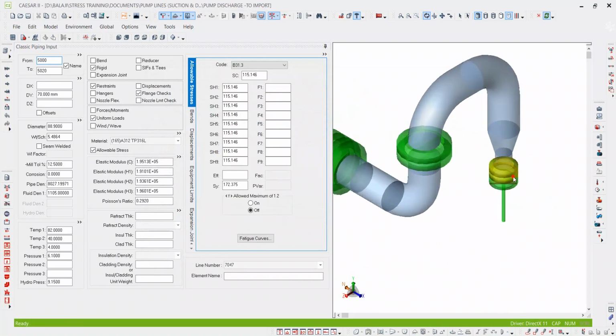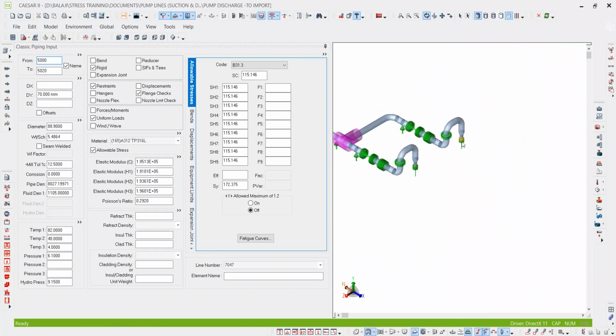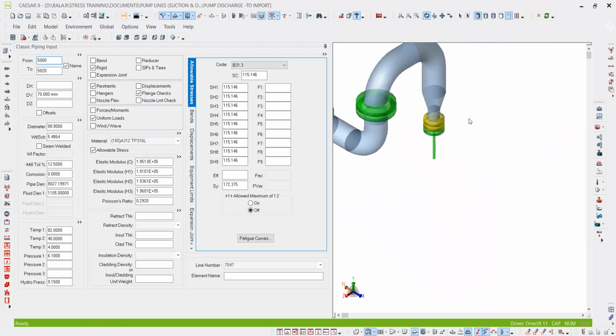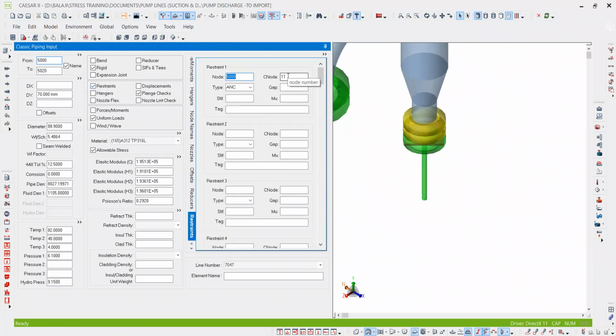So here, what we need to do, that's what I told you clearly. The node number, whatever you use for the other file, should not get repeated. If even one node number is repeated, then it will be an issue. It will not get combined properly. So now you see what I am going to do.